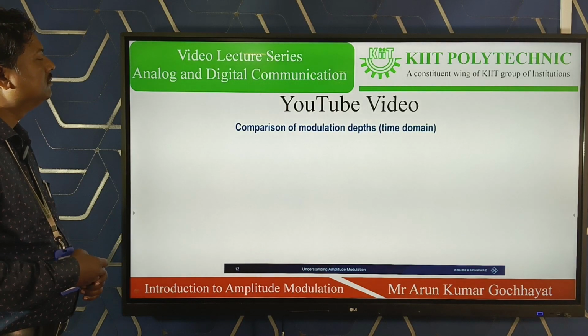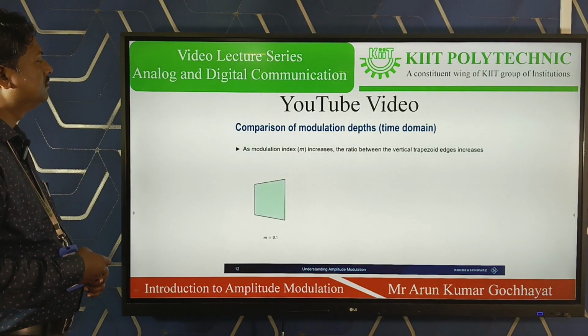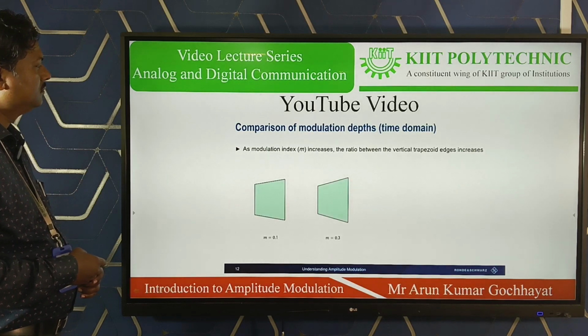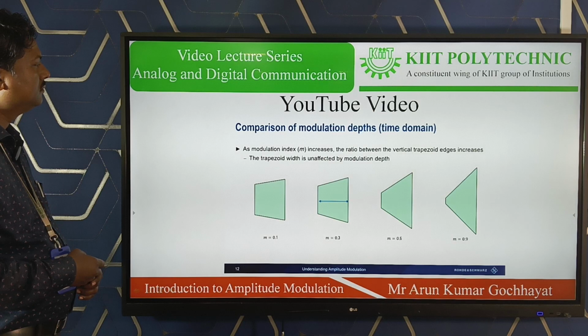The shape of the trapezoid changes as we change modulation index. As modulation index increases, the left edge of the trapezoid begins to shrink, increasing the ratio between these two edges. Note, however, that the width of the trapezoid is unaffected by modulation depth.